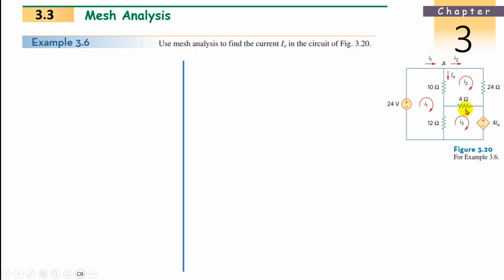Now it is reverse, check. I3 minus I2. Now here, what is this? Entering the plus, so plus 4 I0. We need 4 I0, so what is I0? Later we can substitute. As per Ohm's law, or directly, what is I0? I0 is nothing but I2 minus I1. I0 is downwards, so it is I1 minus I2. As per the loop current. Getting it or not?